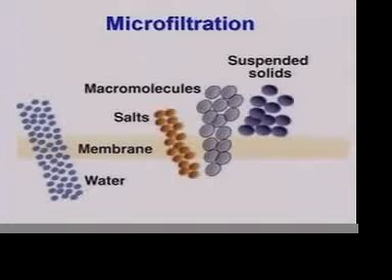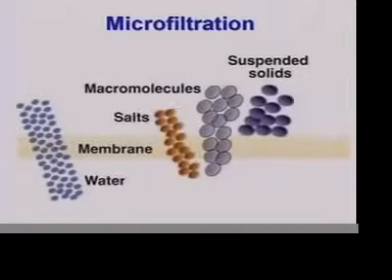I don't care whether they're large suspended solids or submicron down into the colloidal size. If the technology is used to remove suspended solids, it's microfiltration. And here you have the water moving through, salts moving through, macromolecules, which is another way of saying organic contaminants, also pass through, but suspended solids are in particular rejected or held back.